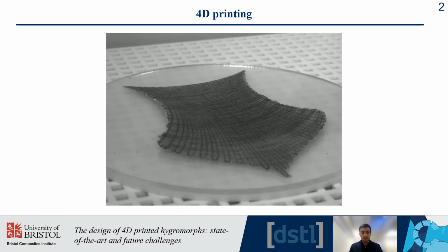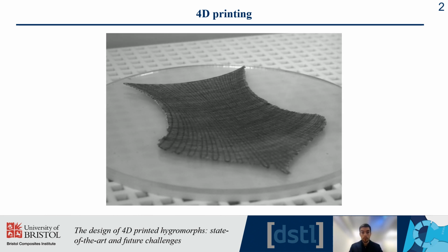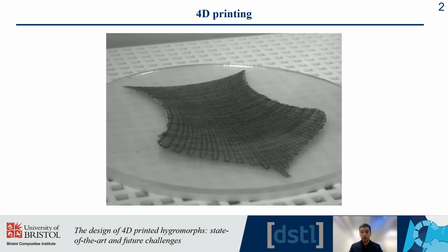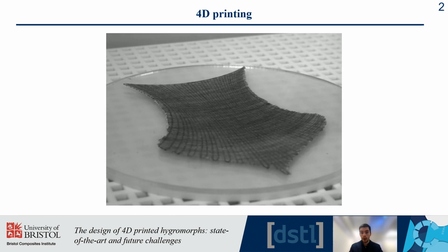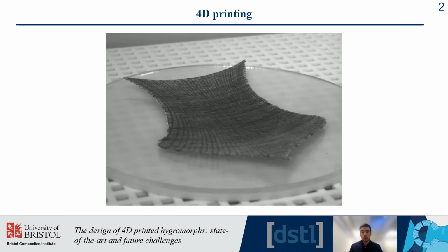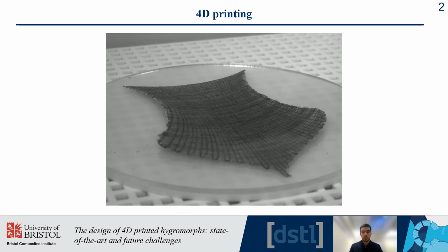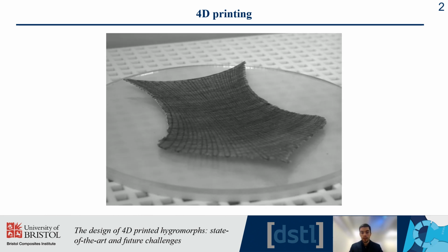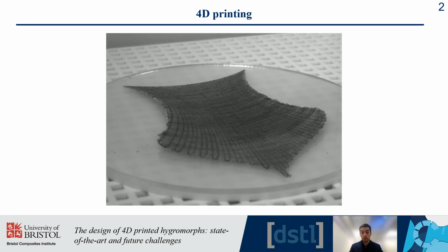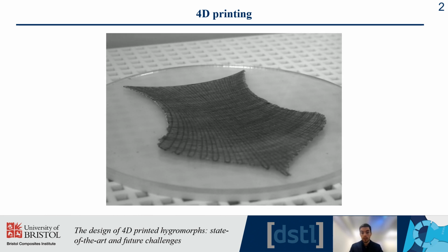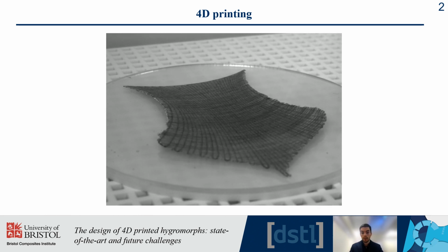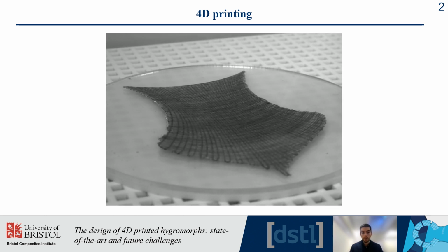An example is given on this slide. In this video you can see an example of a 4D printed structure. It's a 3D printed continuous flax fiber reinforced PLA part, whose transformation is actuation, so bending actuation, when the environmental humidity is modified around it. Basically this part was conditioned at low humidity and then immersed in a high humidity environment, and you observe the actuation on the video.